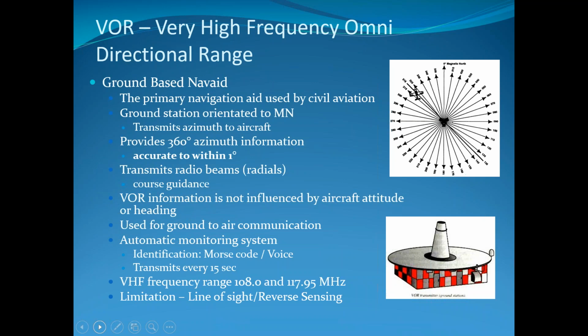So if a pilot is flying down the canyon and he tunes his radio into the ASOS for St. George, he's hearing it. The ASOS is going to be in magnetic. The METAR, if he prints it out on his little printer from his ACARS machine, is going to be in true. That's really weird. How far off are they? That's where you would have your variance. So like John was saying a minute ago, St. George is more or less minus 14.